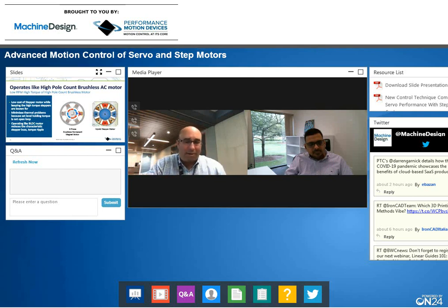Versus, at the other end of the spectrum, you can have semiconductor applications where you're trying to move things very precisely, very smoothly. You don't want the torque ripple, but your RPMs are never very high because you can't afford those accelerations in a vacuum. Things will slip and move around. You can't do it. So regular brushless motors can be problematic in those areas where these solutions can help you out.